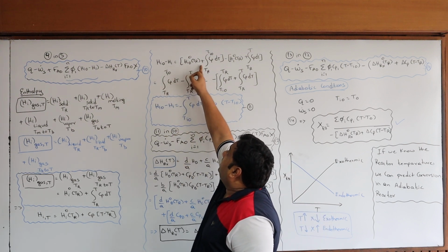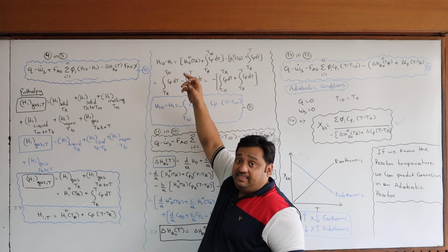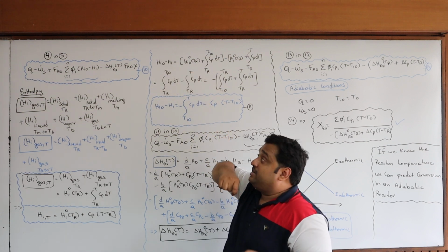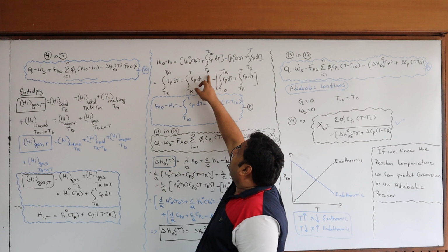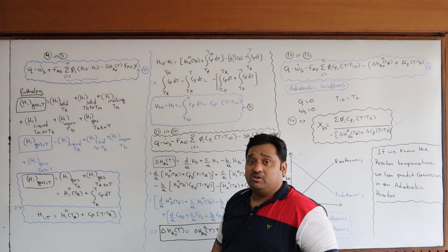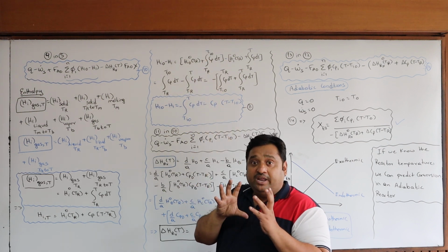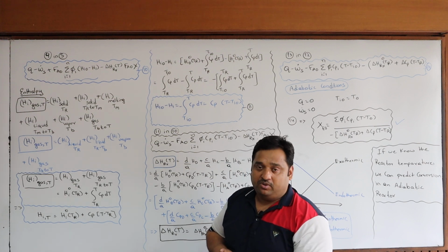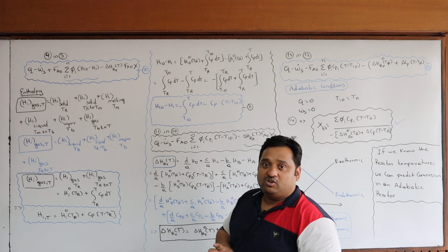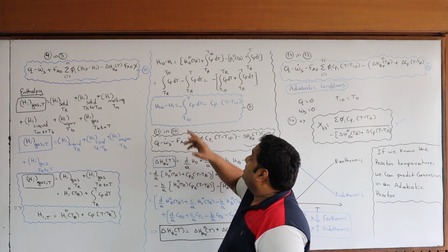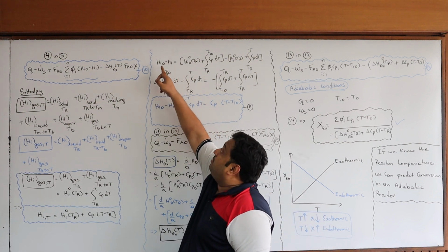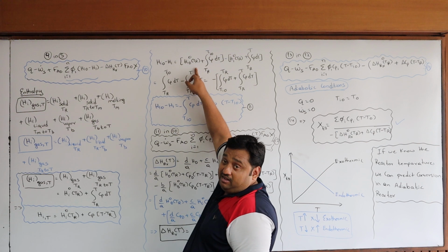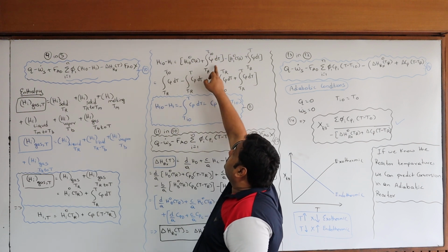The enthalpy of gas inlet to the reactor is nothing but the enthalpy of those gases at the reference temperature plus the integral from the reference temperature to the initial temperature, because all the molecules enter the reactor at temperature Ti0. That is called the inlet temperature of all the gases. So, Hi0 is nothing but Hi0 standard plus the integral from TR to Ti0 of Cp dT.